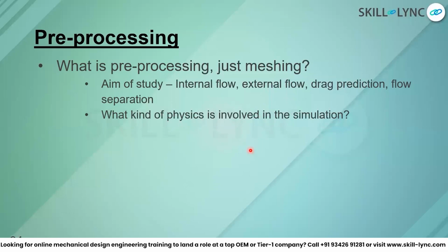If heat transfer is involved, if a solid is involved, what is the material? Material plays an important role because of the conductivity and the specific heat. Convection plays an important role, because if it is forced convection, what is the inlet velocity? How much is the heat transfer coefficient? What is the temperature difference? What is the area?